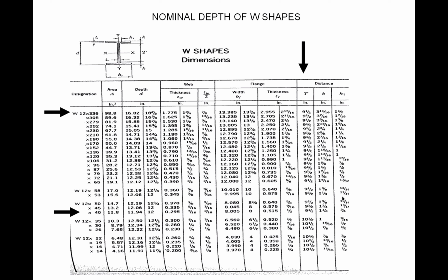Okay, so the intricacies of the exact weights and measures are really for the designer, and then for you on the construction side to know the weight of your picks, the length of your picks, but you don't need to know so much the very finite dimensions as to the thickness of each web, because they should come to you with that already from the plants and be inspected there before they get to you.